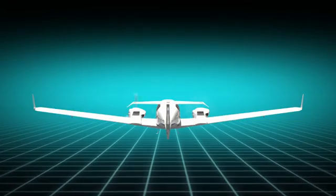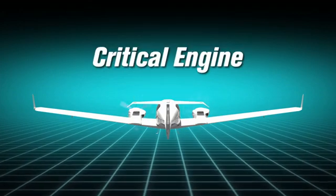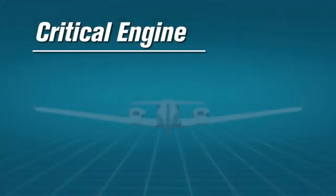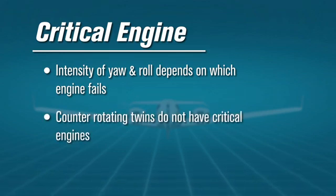Another important concept to learn is the critical engine. This term is used frequently when discussing one-engine inoperative conditions in a multi-engine airplane. In certain multi-engine airplanes, the intensity of yaw and roll produced when a particular engine fails might be different than when the opposite engine fails. This is especially true in multi-engines with conventional rotating propellers. In multi-engines with counter-rotating propellers, the aircraft reacts the same regardless of which engine has failed.